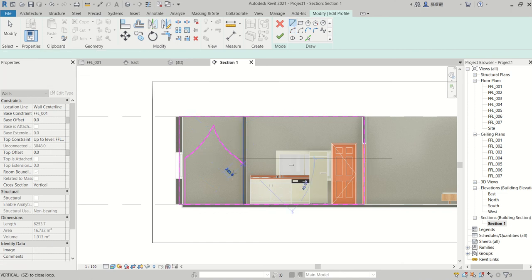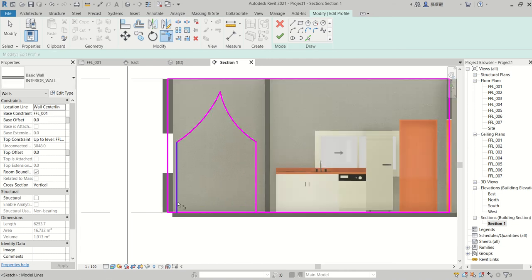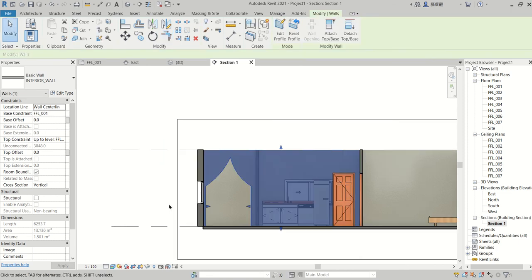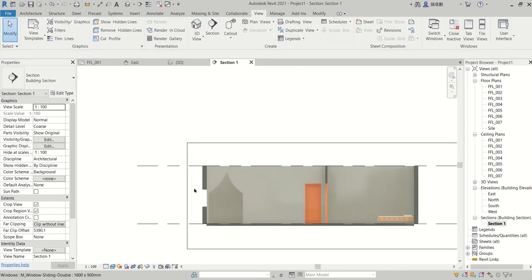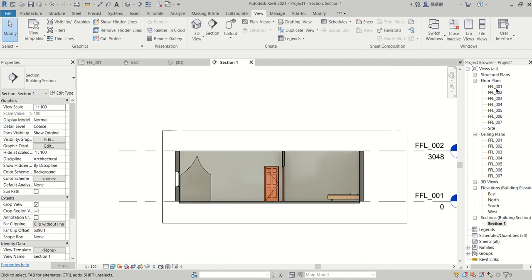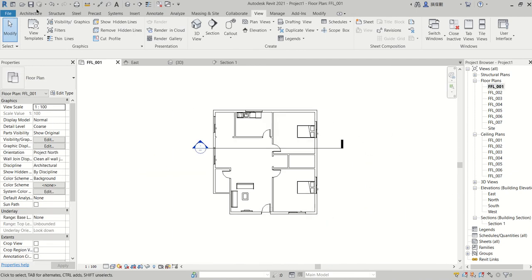I choose this line. I will join it here just like the previous one. I split the element here. Trim. Choose trim. Finish. And you can see how it appears. You can create the size in a way you want. It depends on your creativity and interest requirement also.